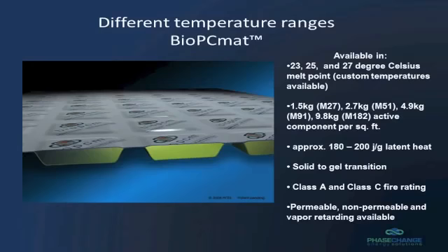For example, in my house, I've got 25-degree phase change material upstairs, and during a hot day, the room slowly climbs from 19 degrees to eventually hit about 25, 26 degrees by the end of the day. Upstairs used to get to 35, 36 degrees. Now it doesn't get past about 26, 27 in the middle of summer.